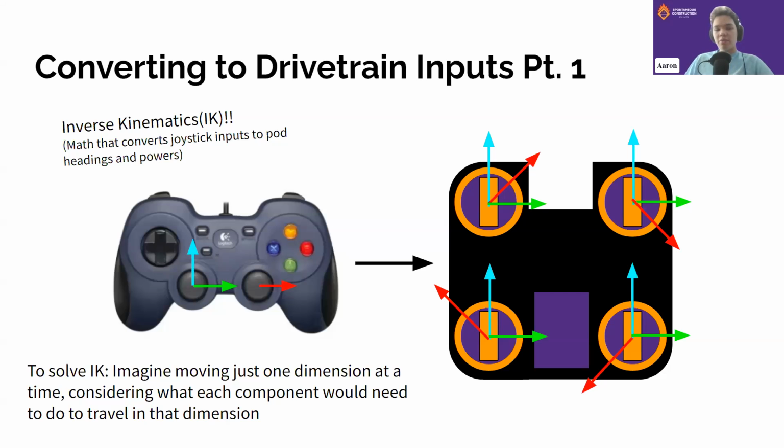There was another question about whether or not we recommend 2-wheel or 4-wheel swerve. I think that it just heavily depends on the type of game, and if you choose coaxial versus differential swerve. Basically, the best option for 2-wheel is differential in any case. And I say that 2-wheel swerve is a pretty effective design, especially in games that don't have any sort of terrain elements, like Ultimate Goal, where the field was completely flat, or even Skystone, if you're not going to go over the center jump thing. Then it's probably a good idea to use 2-pod swerve.